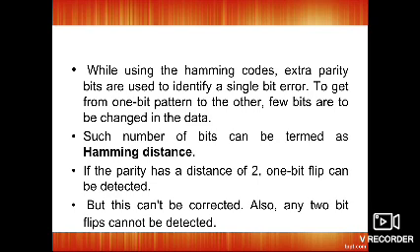So for controlling errors, there are different types of methods. One is the forward acting error correction method and the other is the reverse acting error correction method. The types of errors can be random errors and burst errors. Some of the important error controlling codes are block codes and convolutional codes. The code rate can be determined as r equal to k by n. So block codes are always denoted by (n, k).